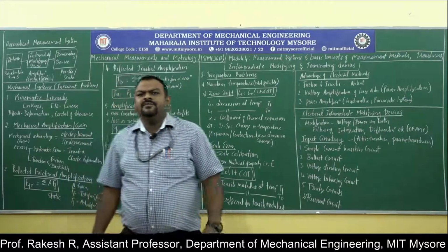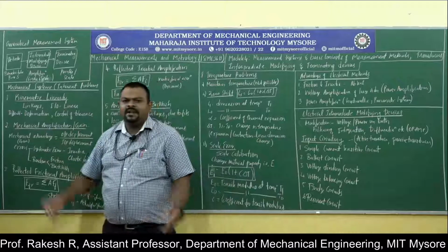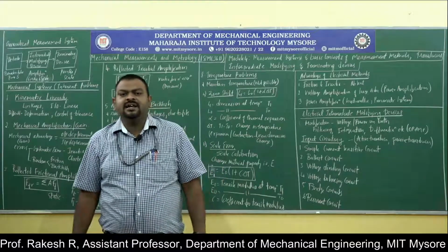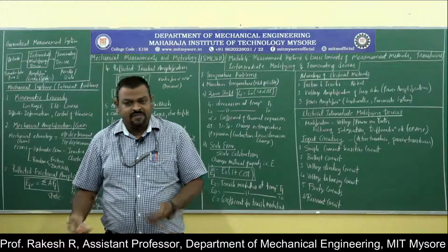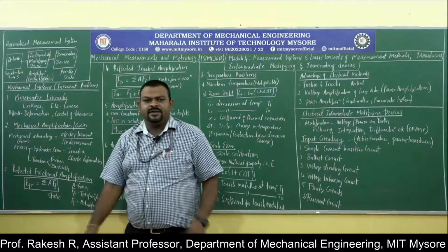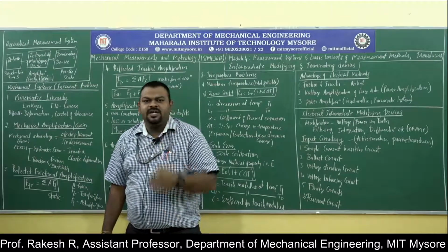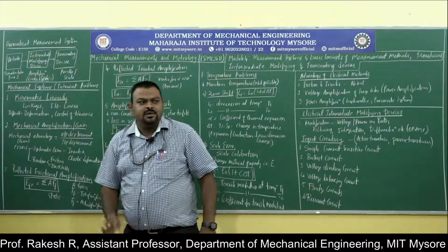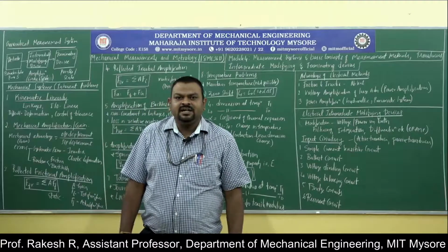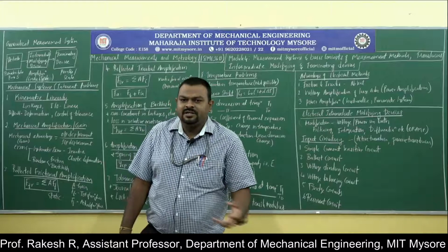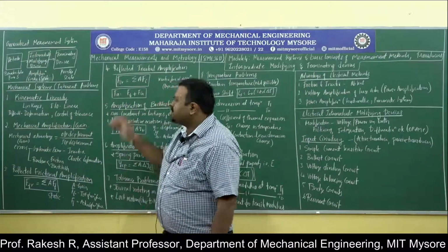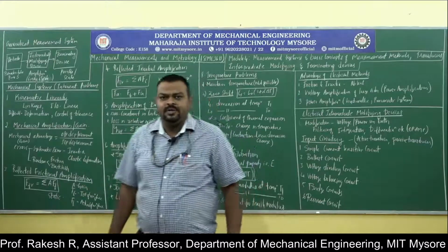In intermediate modifying devices, there are several elements. We can do mechanical, using mechanical linkages, as mechanical intermediate modifying devices. We can also do electrical intermediate modifying devices, where we vary voltage and current. Also electronic intermediate modifying devices, which are circuits, chopper amplifiers, etc. And again there is a CRT output display.